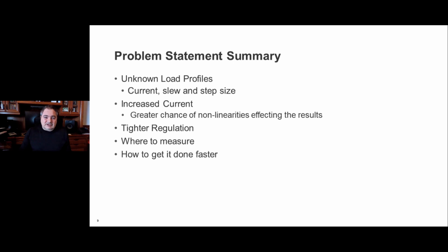As we go down in geometry, as the functionality of these devices increases and the gate voltage goes down and the V-sense or the V-core voltage goes down, then the regulation is tighter, right? If the voltage goes too high, you can damage the device. If the voltage goes too low, then you have a signal integrity issue. You could lose the data. You could have a data integrity issue, more importantly.